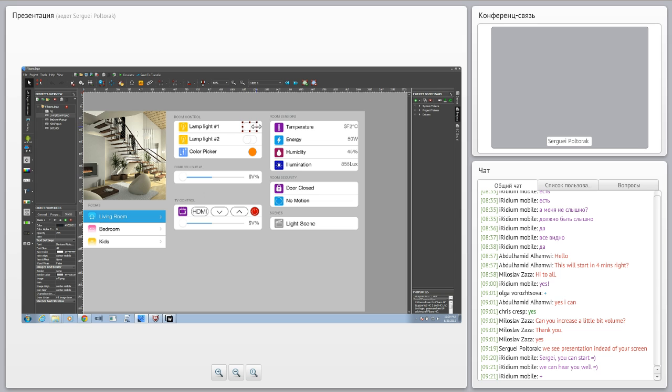Second we need to do is open iRidium interface. We will choose this button to control our switch. On the right we have project device panel. In this panel we need to expand driver section. We have only Fibaro driver connected here, and here we see two sections, commands and feedback.